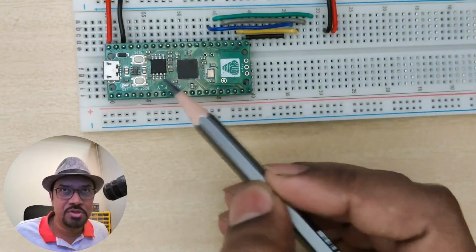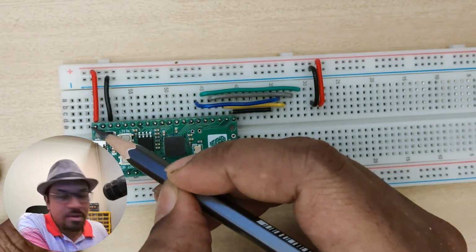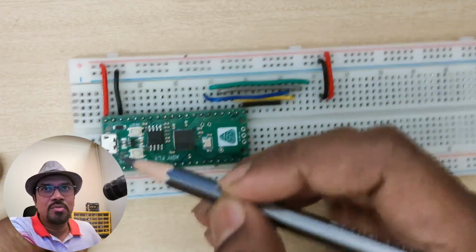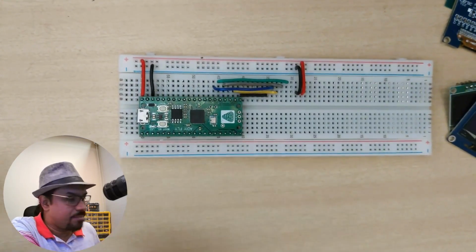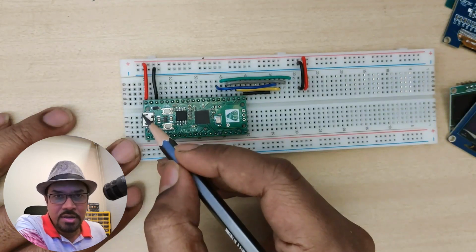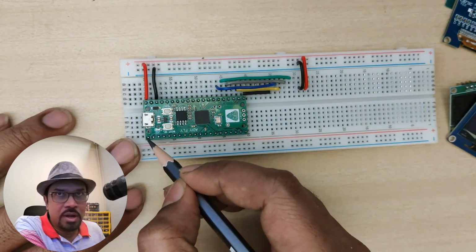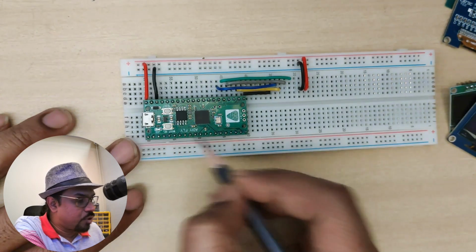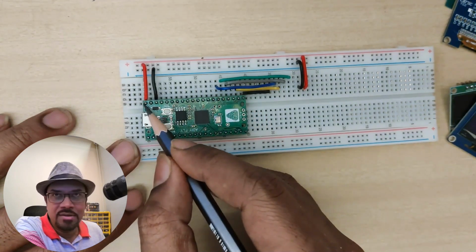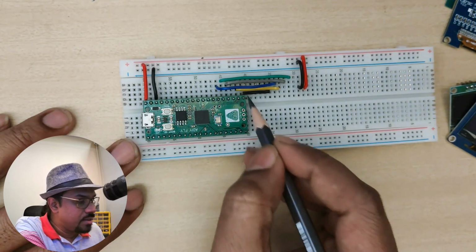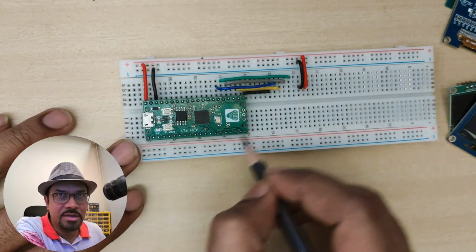And let me tell you about the pin outs which I have configured in here. So first of all, you can see this particular pin, the last pin that you see here. So if you start looking up the Raspberry Pi Pico, let me just try to reduce the zoom a little more so it's slightly better. Yeah. So when you look at the Raspberry Pi Pico in here, you have the micro USB connector in this place, and this is pin 1. You can start counting from pin 1, 2, 3, 4, all the way to pin 20. Pin 21 starts in this corner and it ends at pin 40 here. So it's like pin 1 to pin 20, pin 21 to pin 40. You use this direction for counting the pins, from here, all the way up.